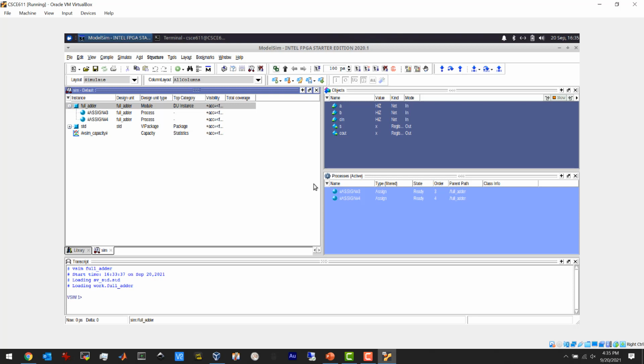Okay, so if you look over here, we have full_adder, and this is going to be the hierarchy of the design shown here. When I was talking earlier about how signals have different names depending on where they are in the hierarchy, and you can drill in and view the signals at different levels of the hierarchy, that's what I'm talking about. This little pane is where you do that. This becomes a tree, and you can browse through that tree. When you click on something in that tree, you're going to get all of the signals that are inside of that scope shown here, right?